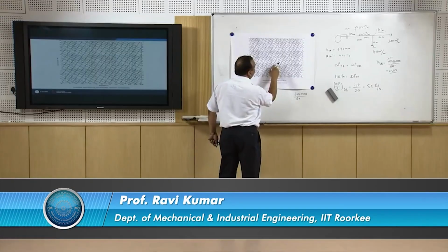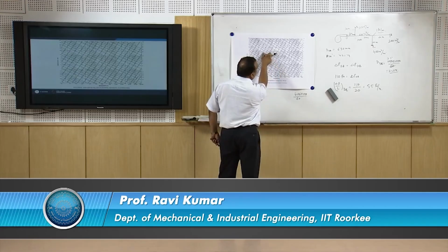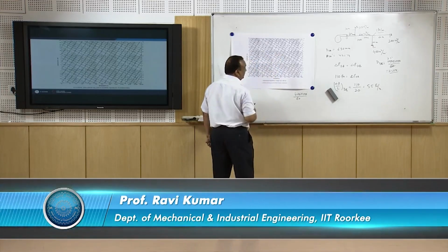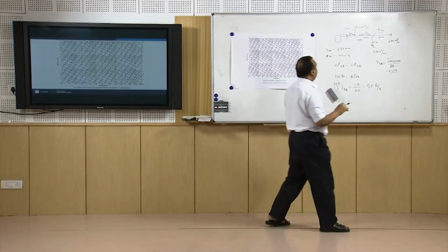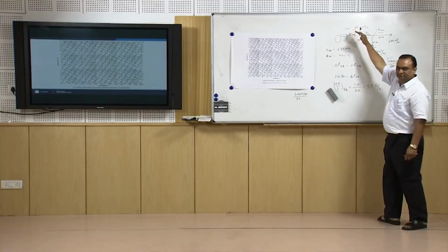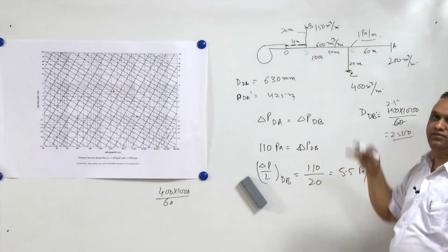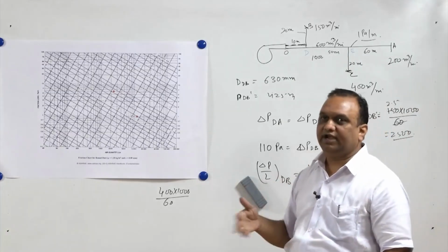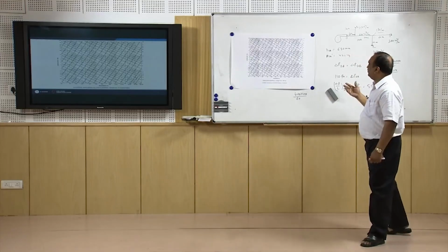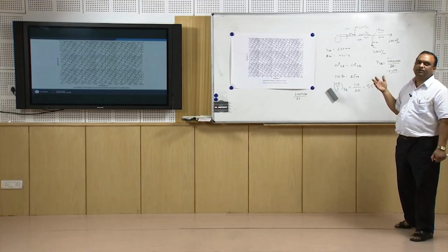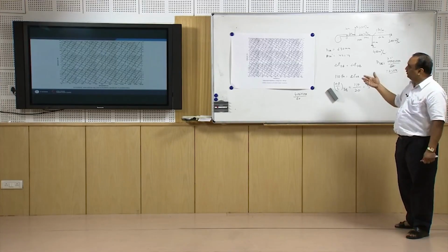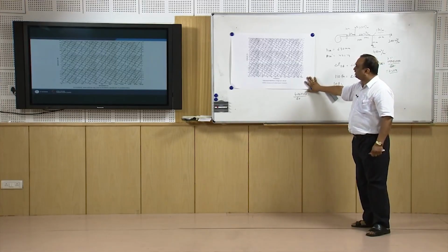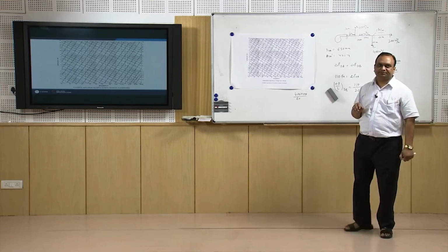Here the diameter is 630 and it is reduced to around 425 mm, and if you reduce the diameter, then we do not require a damper here. So this is how this network can be damper free also. There are many more networks. If you look at the books, you will find a number of duct networks, and you can use this chart for duct design for those networks.